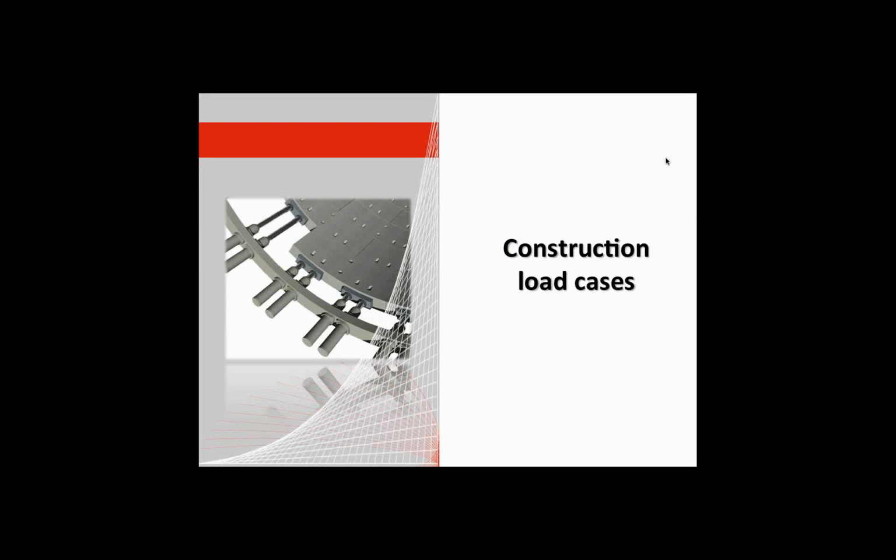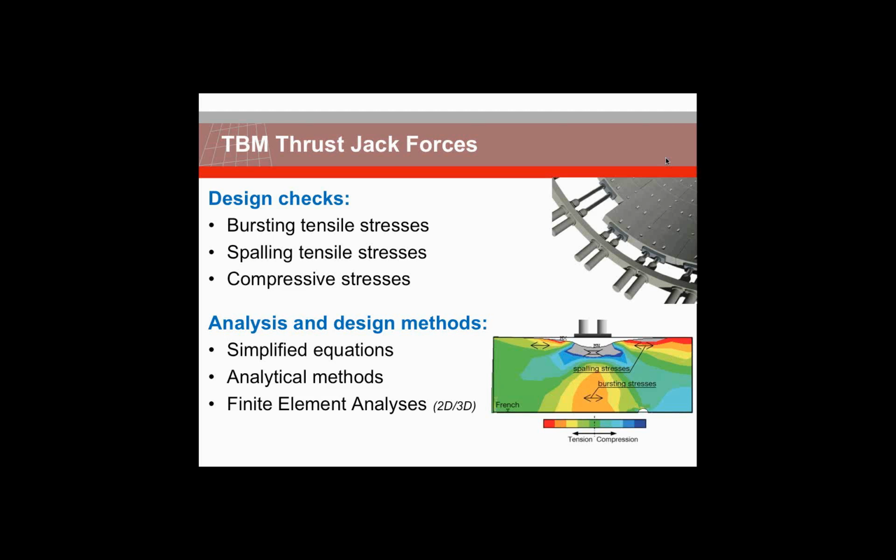Now let's take a look at construction cases that start from the time of segment erection inside the TBM shield up to the time when installation of a ring is completed. And also the annular space, of course, between the segments and the ground. The annular space between the segment and the ground is filled with grout, and the grout is hard.